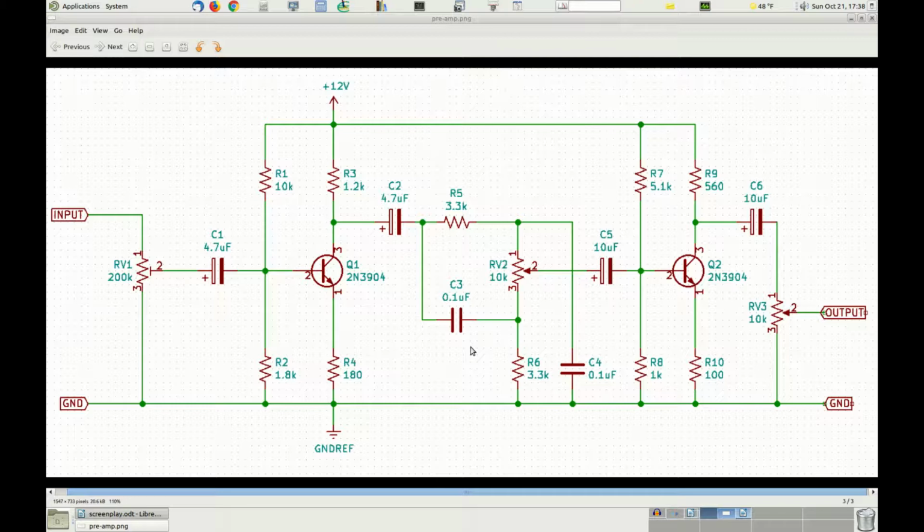Instead, it provides different responses to the vast range of frequencies the Theremin can provide. When the cursor is mostly on the side of terminal 1, the Theremin will provide a sound that is more powerful at the low frequencies and becomes less and less loud when the frequency increases. Vice versa, when the cursor is moved toward terminal 3, the most effective sound happens at the highest frequencies rather than the lowest. This control, therefore, rather than providing a tone control, provides a change in brightness of the sound.